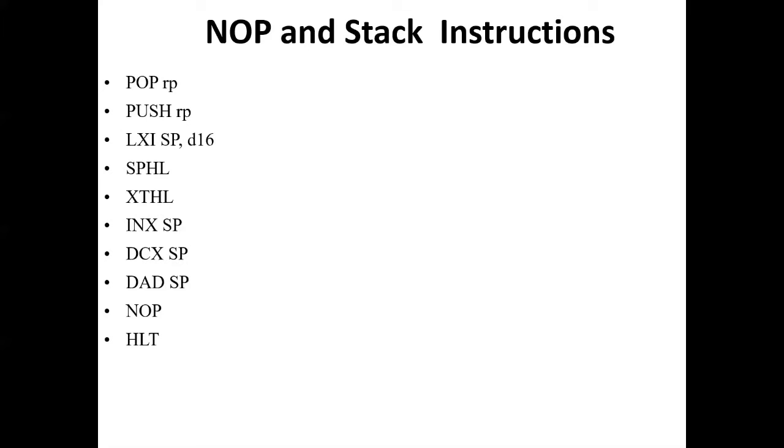Next is SPHL. This instruction loads the stack pointer with the contents of register pair HL. It is an indirect way of loading the stack pointer, and as such it is not quite commonly used. It occupies only 1 byte in memory compared to LXI SP instruction, which is 3 bytes long.